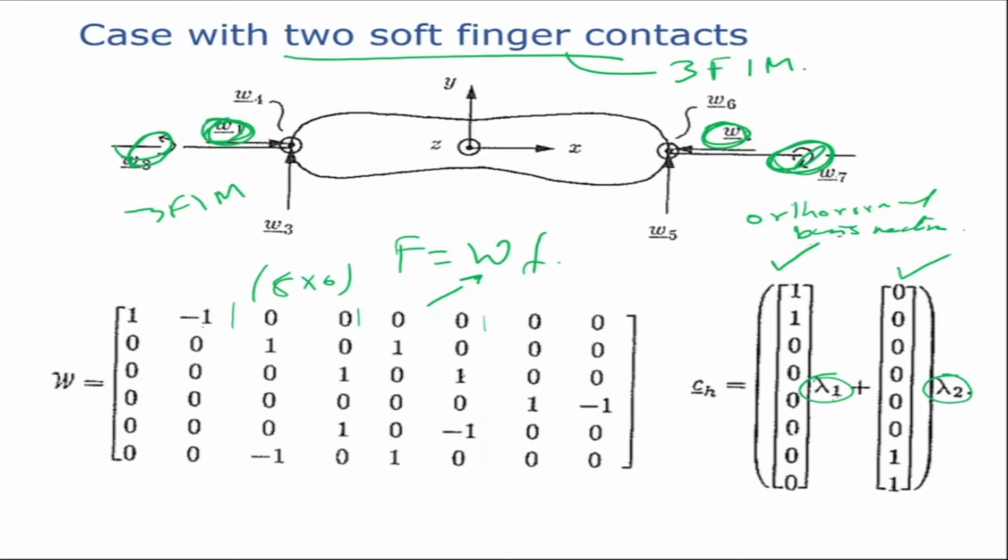So when we talked about multi-fingered hands, we basically have to worry about this case where we have fingers holding the objects, which have positive internal forces and whatever additional forces are required to move the object. So next, let's look at the grip transform for object manipulation.